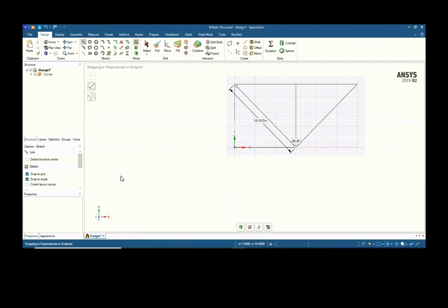All right, so here we go. It gives us lines 1, 2, 3, 4, 5, 6. So these are the lines that build this particular structure. Next, we have to create the areas. Here is a square cross-sectional area.